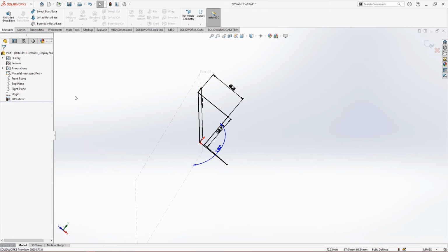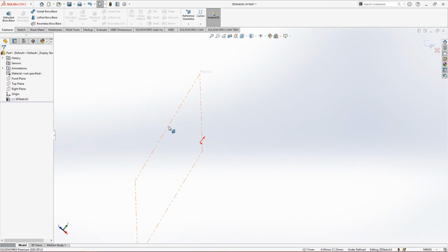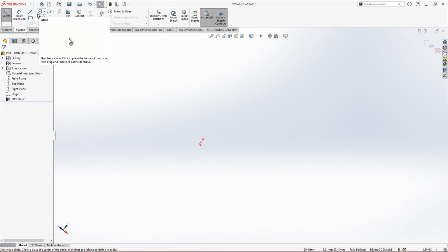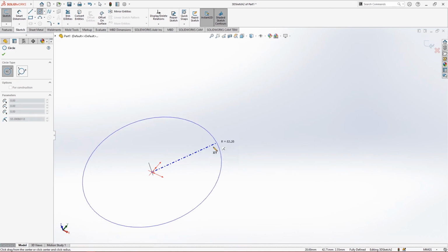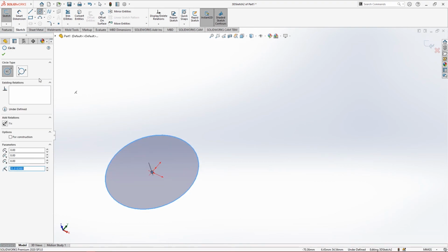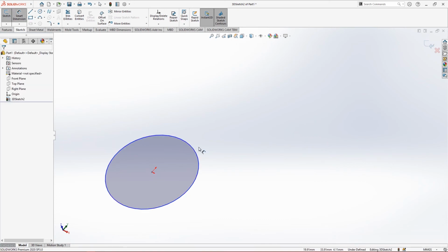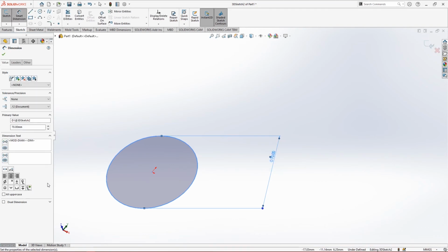Before I conclude my tutorial on 3D sketches, let's just go through one more aspect. One of the 3D entities is the helix. So how do you make a helix? First of all, if we want to develop a helix, we will need a circle. You can make a circle in 2D or whatever, you can do it. For example, I made a circle. I can define the dimensions of it. For example, it is 71. Let's just keep it to 70.